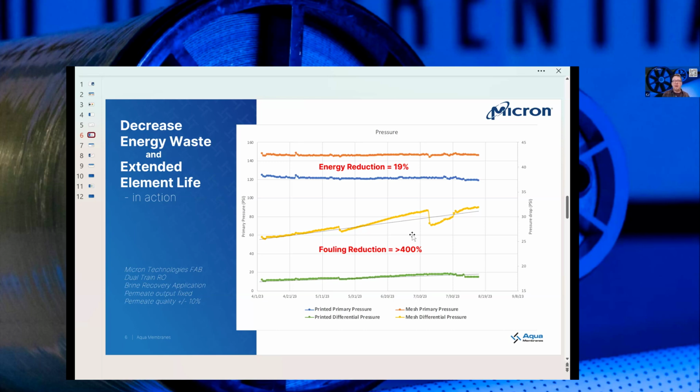There's a lot of things going on in these systems, and to a certain degree, I think it's useful to recognize that it's almost amazing the data is as clean as it is, because this is a system not being run for data. This is producing water inside of the plant. Those specific points where things dropped didn't correlate with cleanings. What they did seem to correlate with was periods where the system had shut down and then started up quickly. So if anything, it seems to be more of a difference in terms of potential, almost early stages of element telescoping.